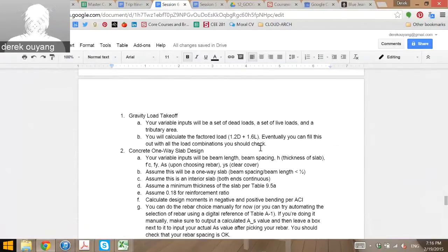Remember when we were doing the hand drawing exercise, we were starting to build what is that bay width, the grid width? In tandem with that, you should be playing on your spreadsheet, because what you decide there, is it 10 feet, 15 feet, 16 feet on the one-way slab span, is only dependent on the amount of load you're expecting, right? And you should be able to see that very clearly once you do the spreadsheet. So you'll know that, okay, if the load is going to be a standard load, then 10 feet on my spans makes sense. And that's the spacing between your secondary beams. So you have to do that check back and forth as you're actually selecting, here are my columns and here are my beams. So that's where this fits in, okay?